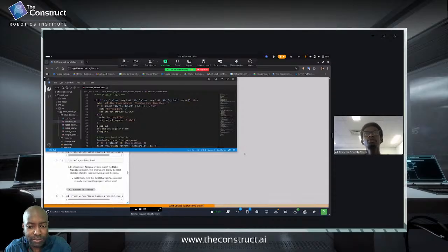As you saw over here, at first I didn't want to test it on the real robot because I didn't want to mess up with it. And so I used simulation a lot with Gazebo and RViz, making sure everything works fine before running it on the real robot. And that's what I always recommend. When you're working in robotics, always start with simulation, then end up with field trial or field implementation. So I made sure everything works in simulation first before doing it on the real robot.